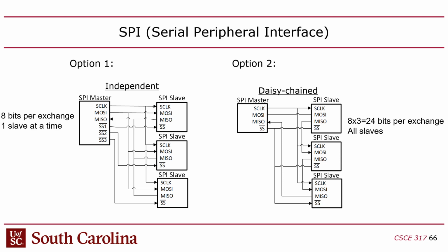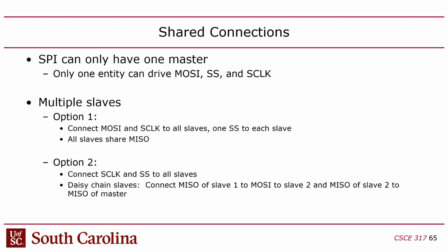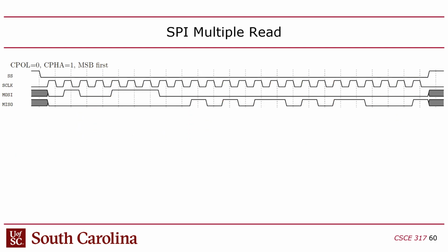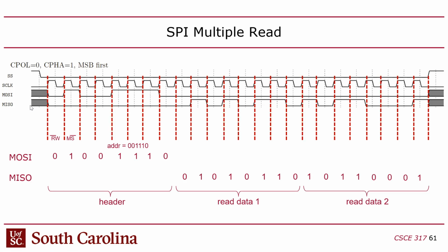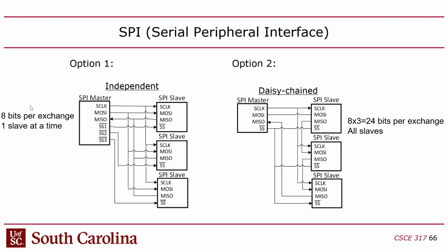And the answer is that it depends on the type of driver. Even if the slaves aren't active, they may still have a driver connected to the pin on their MISO that's always setting it, for example, to 0. In fact, if you go back and look at the timing diagram examples, you can see that before the transaction begins, we have this don't care value for the MISO and MOSI, but the MISO, for instance, may still be getting driven by the slave to 1 or 0 before the exchange happens. So the goal is to have it not do that.